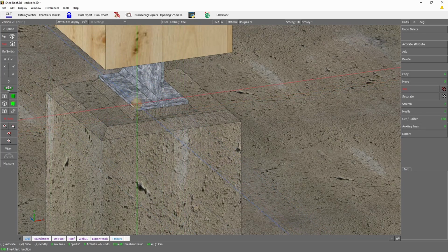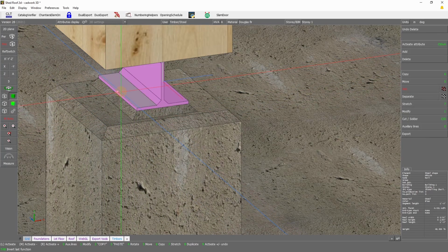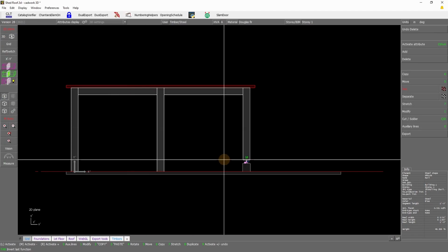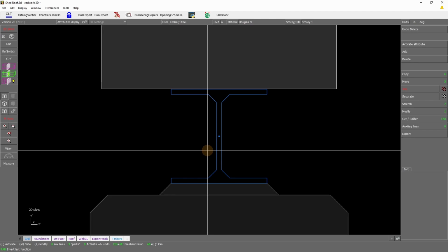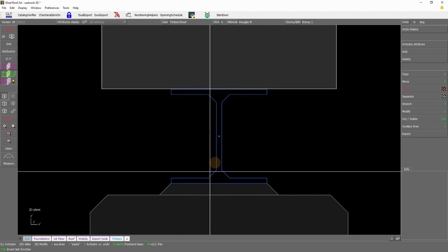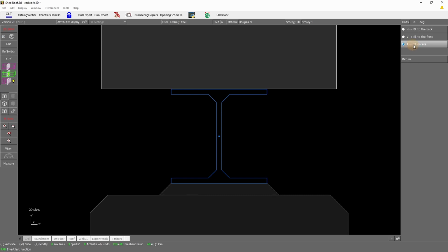Okay, so here we are going to add that plate in the middle of that beam, so we can select directly a point here to use when we enter a plane aligned with Y. So Alt Y, and we just select that point with the left click. Since we want the plate to be in the middle of the element, we have to make sure that we will be adding the element on the axis. So set to A, and now we are going to add a panel, excuse me.